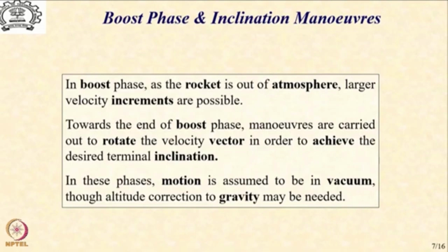So in many realistic cases, up to about 75 kilometers, we still assume that some amount of drag, maybe quite small, is applicable for more realistic and accurate solutions. But for initial configuration design, we generally find that beyond 40 kilometers, assuming the atmosphere to be absent gives a fairly good estimate of the launch vehicle performance and its trajectory.